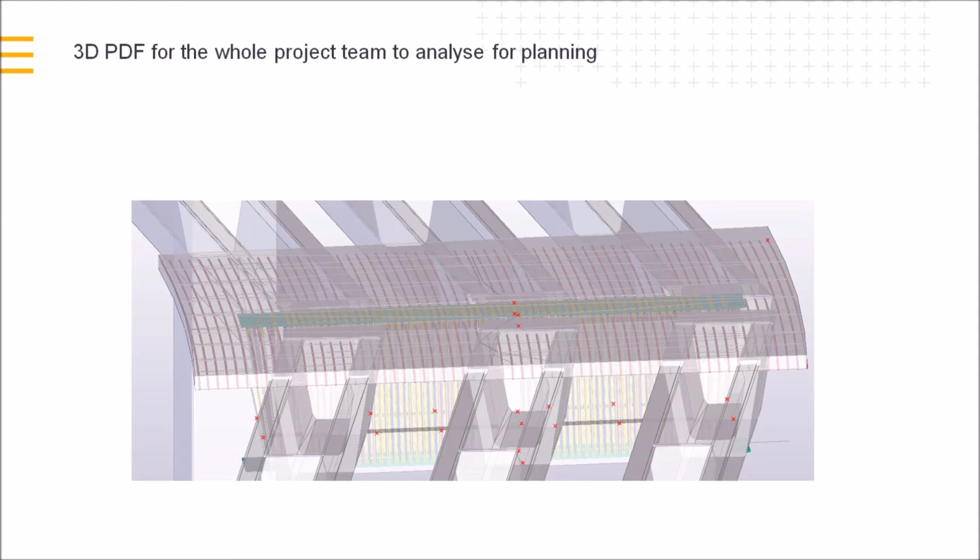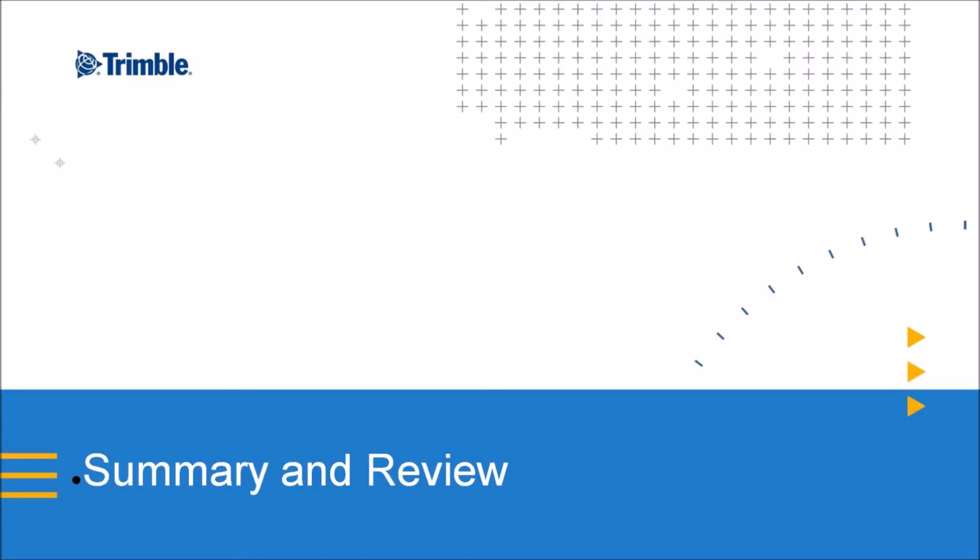based on the model, the slab rebars may not pass through the crosshead starter bars. One solution that they are looking for is to raise the slab and premix so that there will be no rebar clashes. Another possible solution is modifying the rebar sizes and spacing to fit into the crosshead starter bars. All of these were possible because of the 3D PDF, possible to visualize, which comes from the Tekla structure with rebar detailing model.